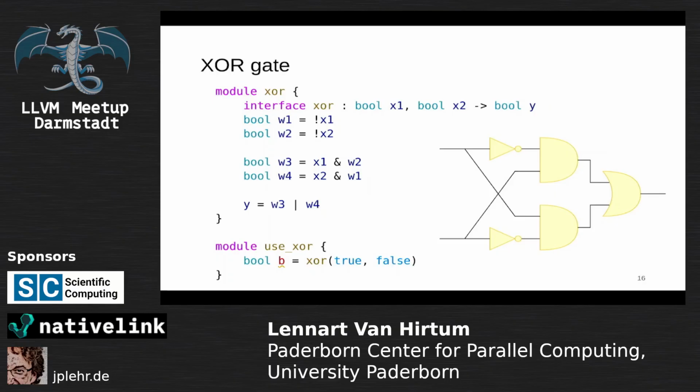We have defined the module here. It's called XOR. We have our two inputs, we have our output, and then a bunch of intermediate wires. These directly synthesize to logic. It's not that you go through this statement by statement and execute it. No, it directly describes the structure, the data dependencies between your wires. And this is a critical thing that sets it apart from software languages, of course.